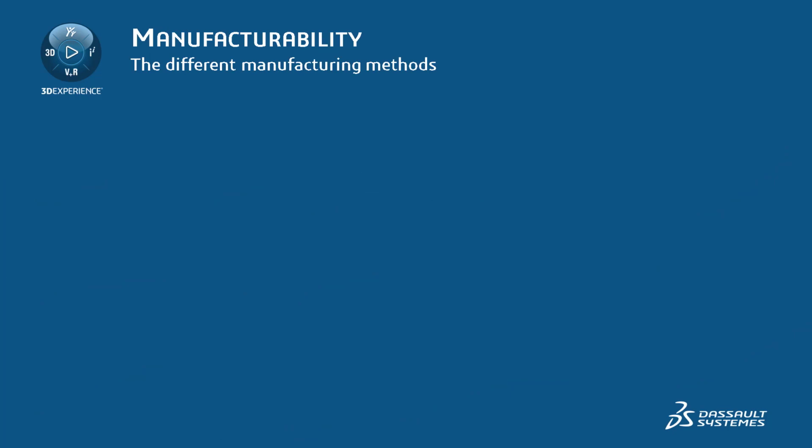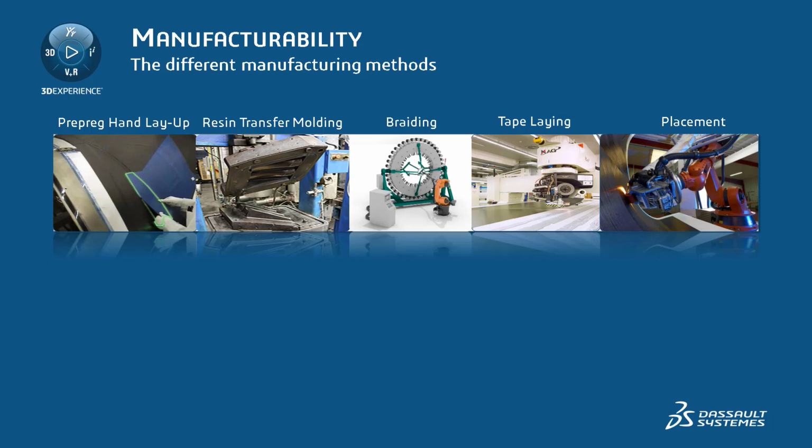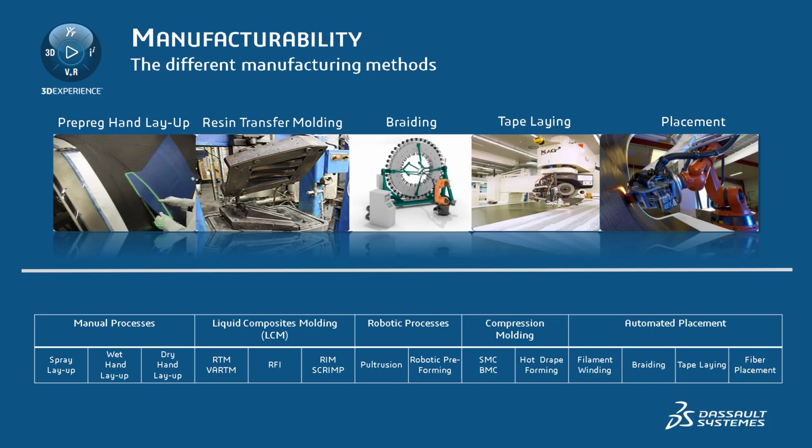Finally, let's introduce the manufacturability of composites. A large number of composite manufacturing processes have been developed over the last 40 years, including contact molding, compression molding, vacuum bag/autoclave molding, rotational molding, resin transfer molding (RTM), tape wrapping, filament winding, pultrusion, expanding bladder molding, etc. All these processes have several characteristics in common. The reinforcements are brought into the required shape in the tool or mold. Resin and fibers are brought together, possibly under elevated temperature and pressure to cure the resin, and the molding is stripped from the part once the resin has cured.